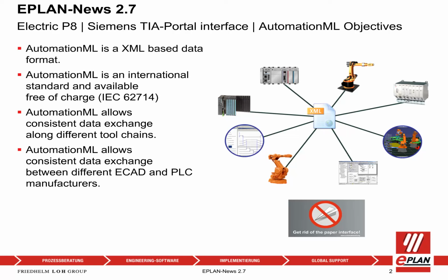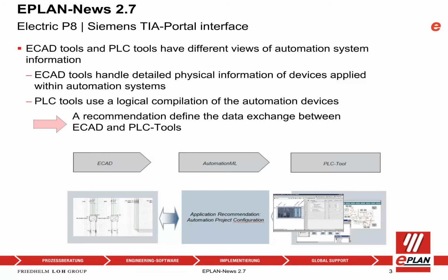EPLAN Electric P8 Siemens TIA Portal Interface, AutomationML. Objectives. AutomationML is an XML-based data format. AutomationML is an international standard and available free of charge, IEC 62714. AutomationML allows consistent data exchange between different ECAD and PLC manufacturers.